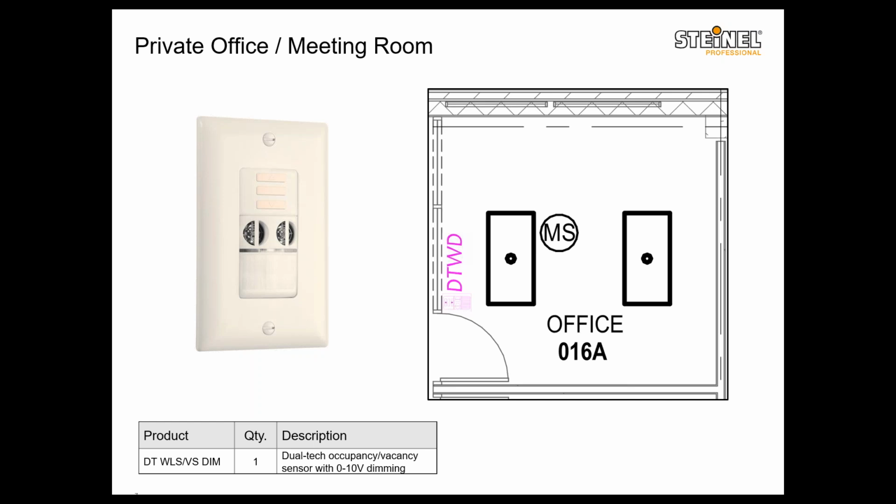Probably the monitors are sitting between you and the switch. So you need to get around that line of sight issue that you have with PIR sensors. You need a dual tech sensor to see that the room is occupied, even though there are two monitors or two big screens blocking the person in that room.